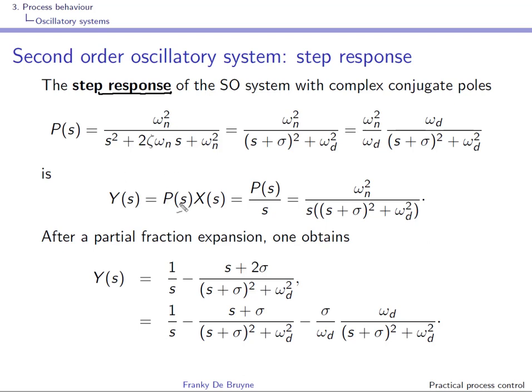You can of course also obtain the step response of this second order oscillatory system. Well, you have to take the transfer function and multiply by 1 over s. This is what you obtain, right? And to compute the inverse Laplace transform, you need to perform a partial fraction expansion, and this is what you obtain.